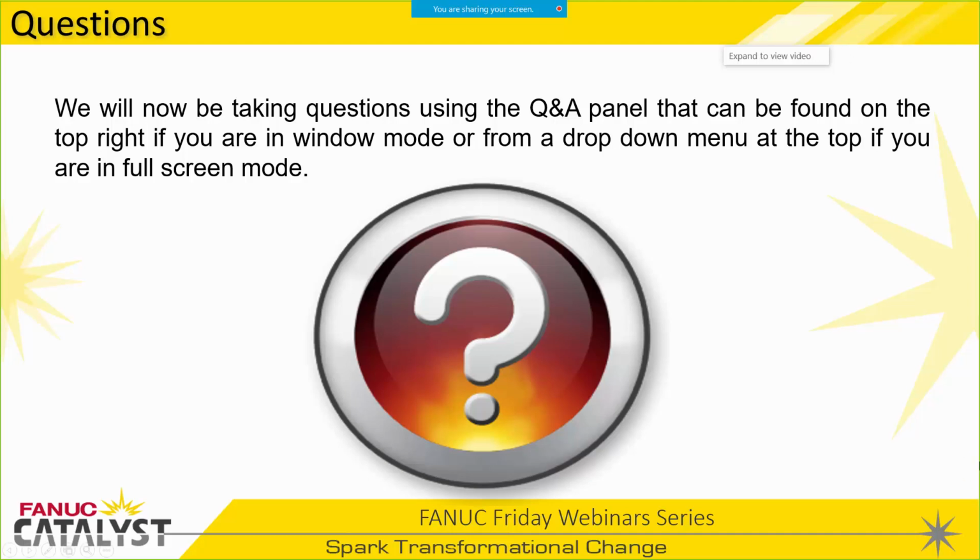Okay, with that, I'll turn it back over. Oh, sorry. One more question here. Do you still need to use a pointer for calibration in iRPickPro for the grid when the camera is upstream of the robot? Well, in iRPickPro, you really don't need to calibrate the camera. If you're talking about the iRPickTool, yes, you still need to use a pointer. There is an auto grid frame set or an auto track frame setup which uses a camera. So in that case, no, you don't need to use a pointer.